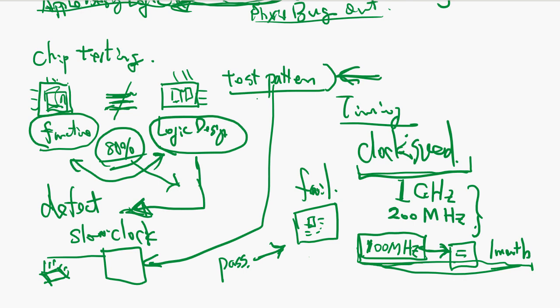what we like to know is that it's guaranteed to run at 100 megahertz. With this microcontroller, we can use it for some controlling, but there's no guarantee because a test pattern cannot test 100%. It's only screening. This is called screening.